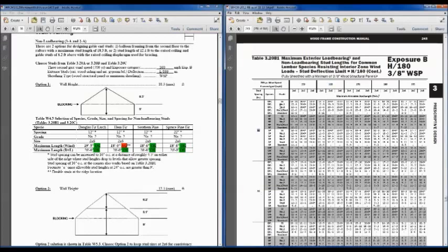And let's just do the Doug Fir Larch number 2 and work across here, and it ends up requiring a 2x6 to get that 18. It's actually 19-foot 5 that works, so for our wind loads that works, and for a non-load bearing stud, the maximum allowed by the code is 20-foot length, so we're still within the code limits as well. So wind loads work at 19.5, and the code allows for dead and live on those non-load bearing walls of 20 feet.